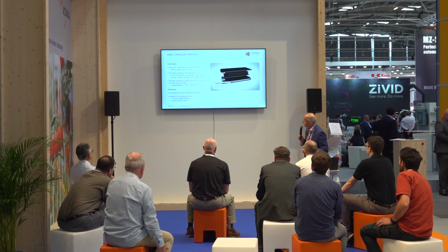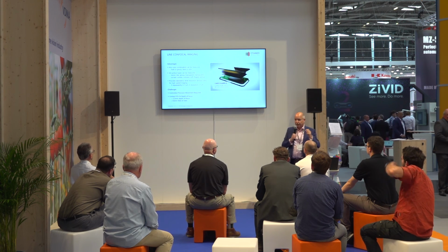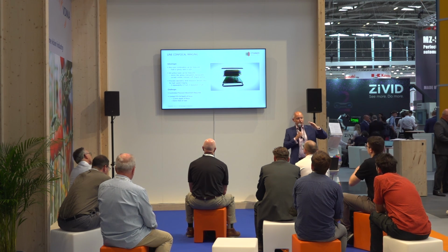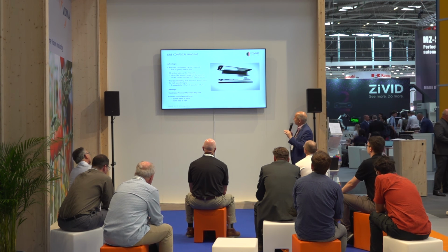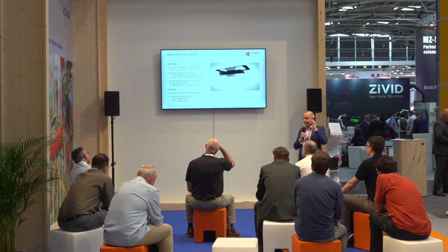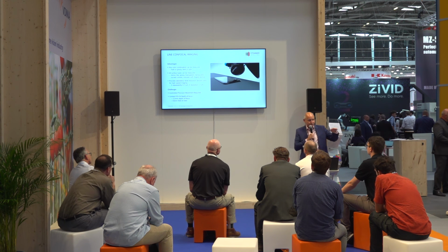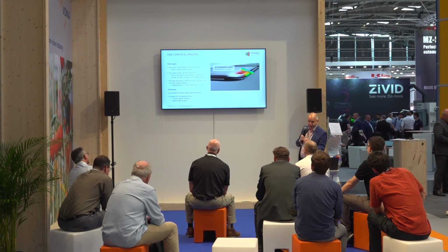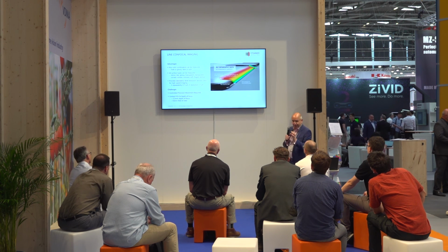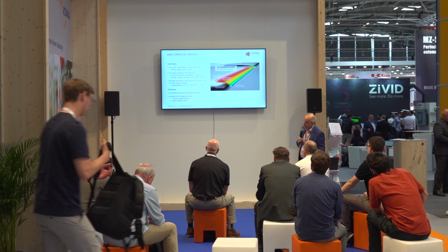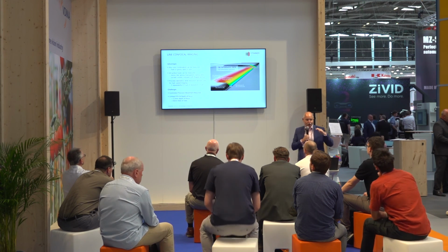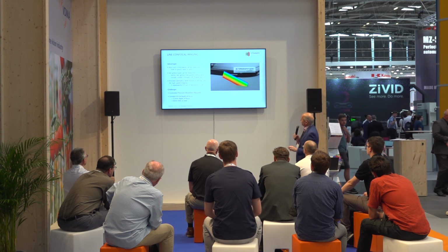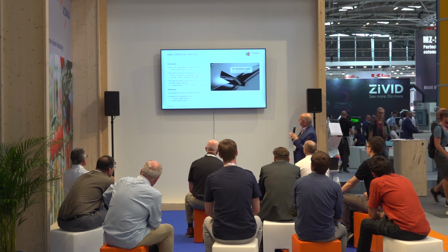Now this application is going to take you through the other thing that this gives you, because it's looking at all the different lights at the same time, it can see multiple levels translucently, of different levels in a material. So you can see translucent materials, layers of glass, layers of film, and get all of the measurements at the same time. We're talking Z repeatability of 0.1 of a micrometer. We're talking very small fields of view, 5.5 millimeters, very, very small. And you have to have this on a granite stage, because any movement is going to completely destroy your measurement. But it really gives you an idea of the way that the data comes through.